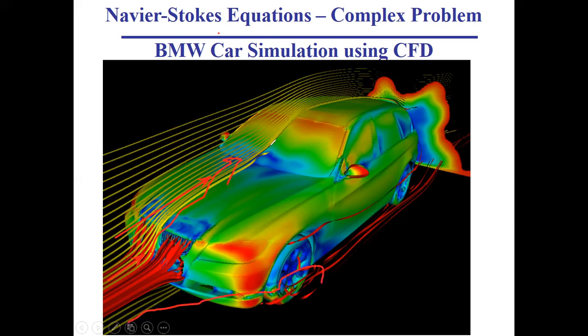Due to this, a total resisting force develops on the car, which we call the drag force. So using the software, you can compute the drag force at each location and do the integral, the summation, to find the total drag force acting on your car. And this will allow you to compute the drag coefficient.